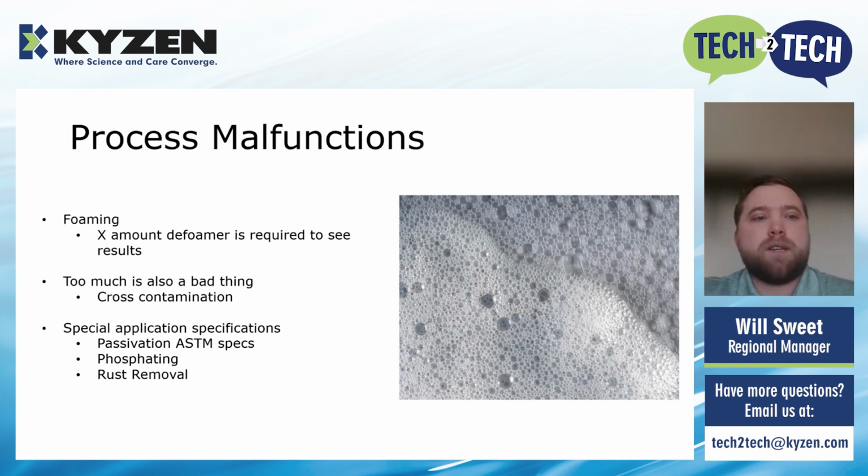And finally, process malfunctions can happen if you don't have proper concentrations, in particular foaming. X amount of defoamer is required to see results in baths, especially large baths. So if you don't have enough chemistry in the bath, you also do not have enough defoamer in the bath. So if you're cleaning a soil that is particularly foamy, you're going to want to make sure that you have enough product in there so that the foam can be killed by the defoamers in the product.